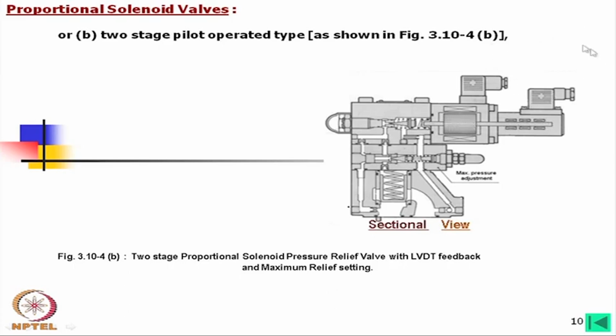Then further it controls. The control unit is outside, and sometimes the control unit is inside. In other words, I would say in this case there is a card to drive these two, and in that card there will be some position feedback control of this solenoid, that means this spool end. Now, there is a main spring, and this spring is just to position this poppet, and this is the varying orifice which is controlling the orifice size, and by that the pressure control.